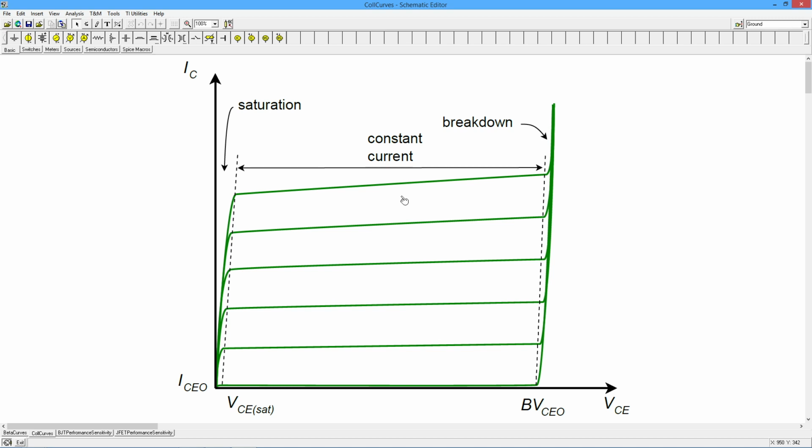We tend to think of beta as being a certain value, maybe for a certain temperature, but do we always have in the back of our minds that, wait a minute, that actually depends on the collector-emitter voltage? There is going to be a variation. Not a huge variation, it's not going to double or something like that, but there is a variation. And will that impact the overall circuit response? As I said, it would also change things like the capacitance of the device.